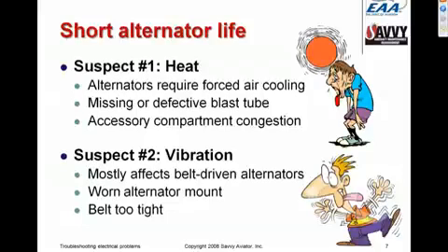So that's the other thing to check in the case of an airplane that's going through a lot of alternators, is to make sure that the alternator is not subject to excessive vibration, and particularly in the case of belt-driven alternators, make sure that the alternator mount is secure and undamaged, and that the belt tension is correct.